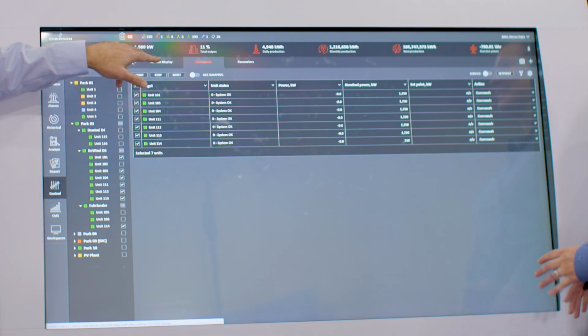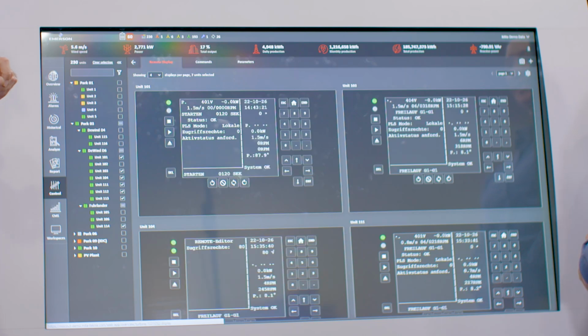What's more, we have a feature that's very exclusive to this product. Inside of your wind turbine tower, a lot of your wind turbines have a display inside the tower itself. We used to call them two-line displays. And the technician might go in there and manually shut down the turbine, change the yaw, change the blade pitch, do some parameter changes directly inside the turbine itself.